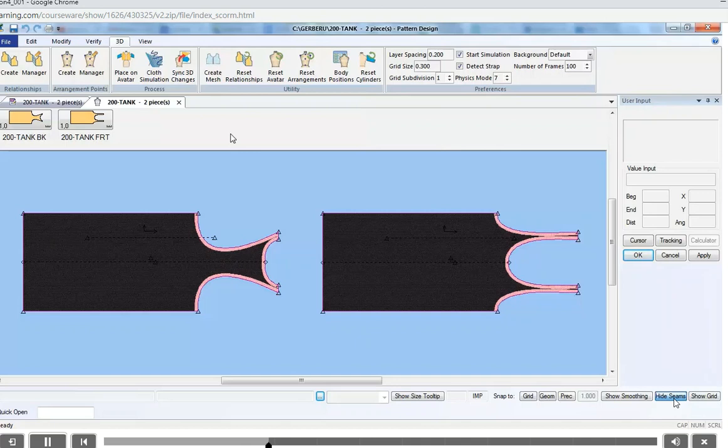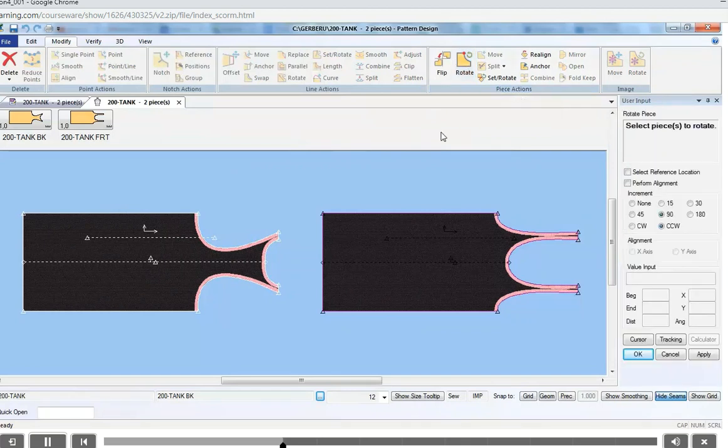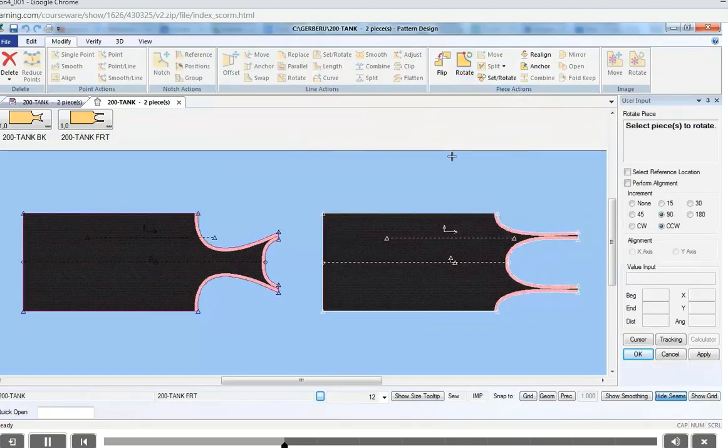With the desired pieces placed in the 3D workspace, orient the pattern so they follow the aforementioned rules and as shown here. We will take the as input orientation and use the rotate function in order to correctly orient these pieces for 3D. We first select rotate from the modify tab and then ensure that the correct options are chosen in view. We then select the piece to rotate and continue to utilize the function and move pieces until all pieces of the model are correctly positioned for 3D.